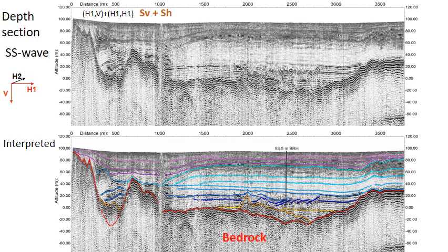The top of bedrock interface shows a deep basin and a gorge to the left. High reflectivity gravel with stratified sand can be interpreted in the section, followed by the first horizontally polarized marine clay 1 and the vertically polarized clay 2.